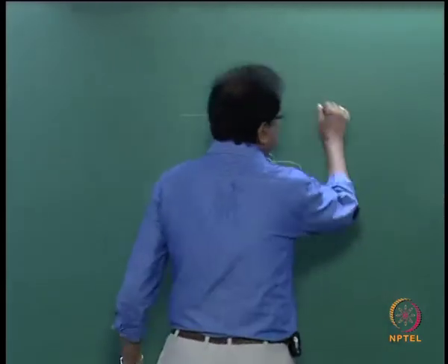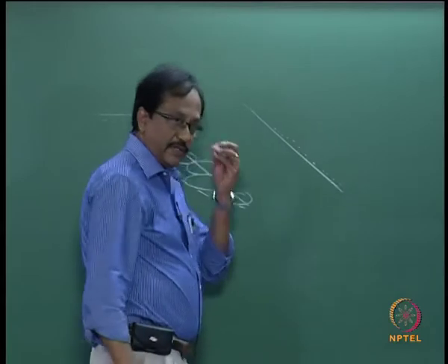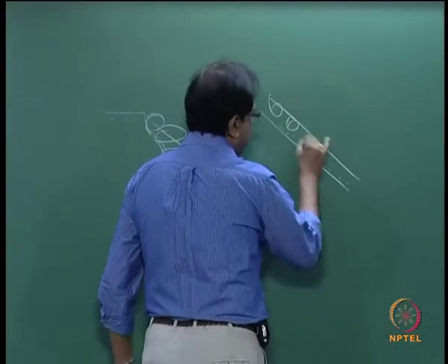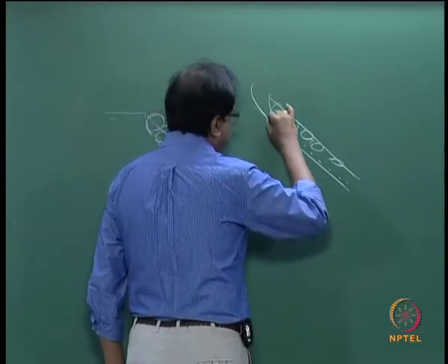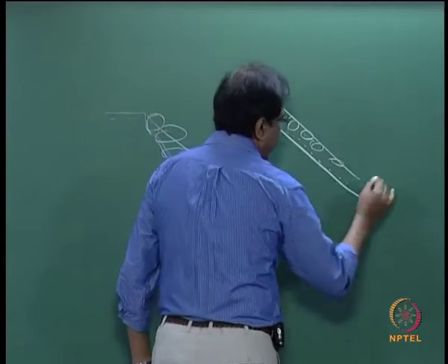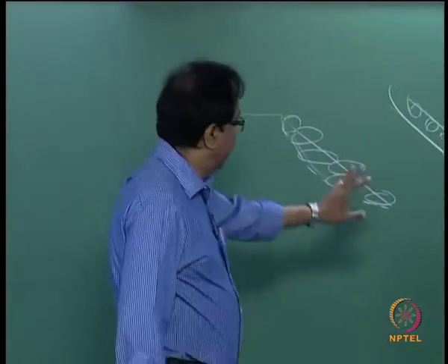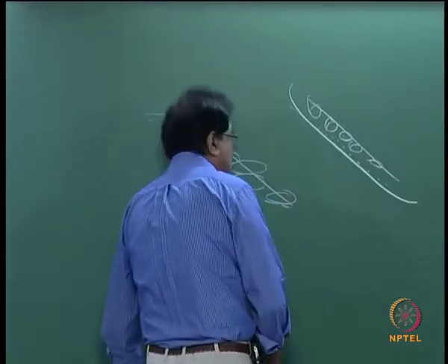Always remember that when you want to protect a slope, you have some kind of a filter layer, over which you have the stones. Now these days we have what is called the geosynthetic material, that is the geotextile, over which the filter layer is placed.